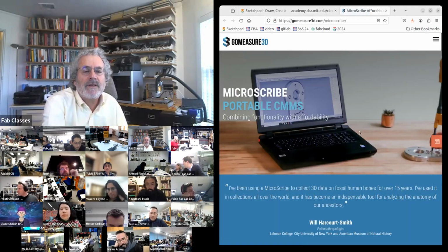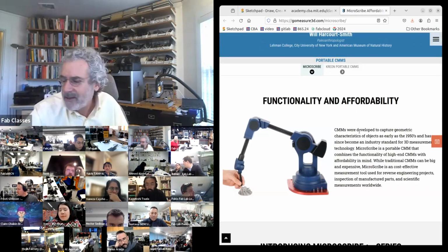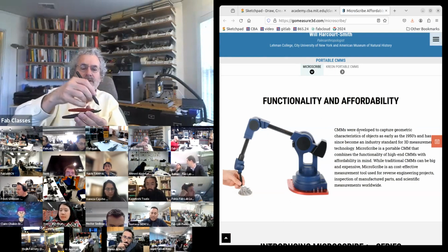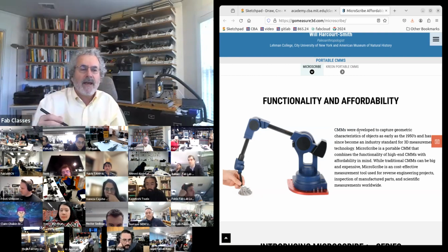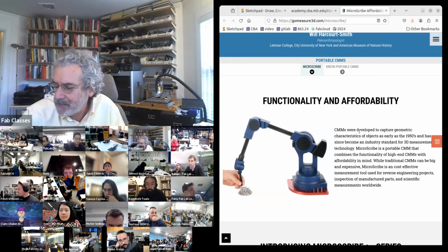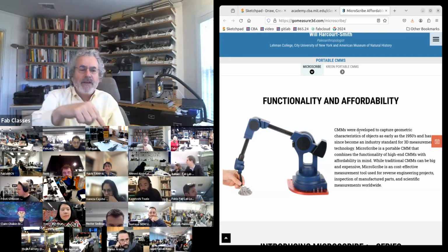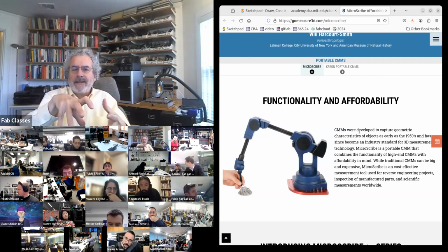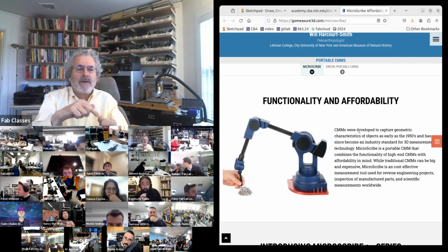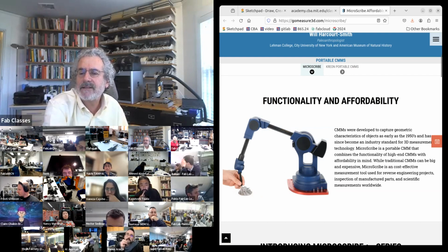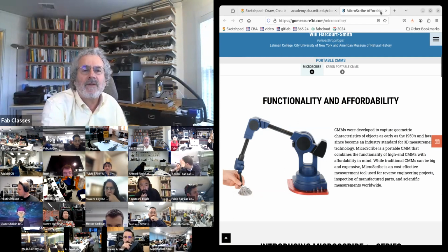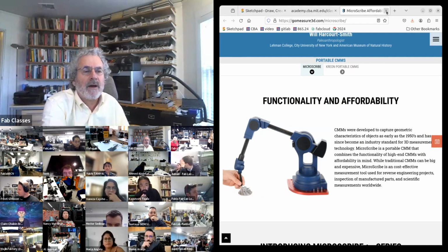Then this is a coordinate measuring machine. This is an arm. And so this seems like it could be annoying. What you do is you manually touch it and you click a button or a foot pedal and you touch different places. But what's nice about this is instead of scanning automatically, you figure out where to scan. And so this is used, like when Frank Gehry makes a model of a building, this is used to digitize it because you add value in the scanning process. You add value from where you probe it to just get the most relevant points for the design. So those are useful.